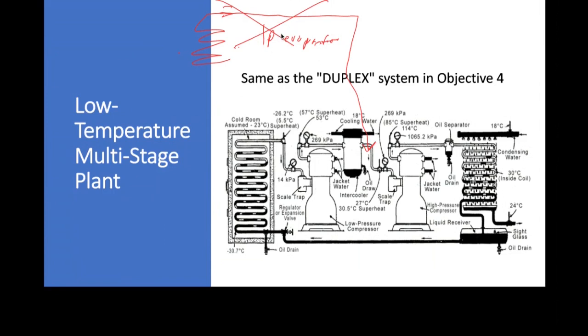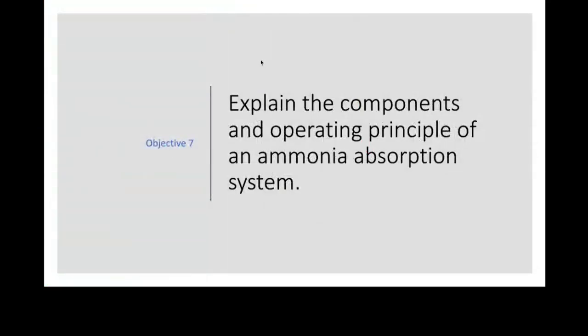If we had an intermediate pressure evaporator that fed only into the inlet of the second stage compression, then we would call this compressor down here a booster. But we don't use the term if we don't have an intermediate pressure system combined with a low pressure system. So you can read more about that. We've basically covered it all. It's a little bit muddy in the third class, so hopefully I've cleared away some of the mud.